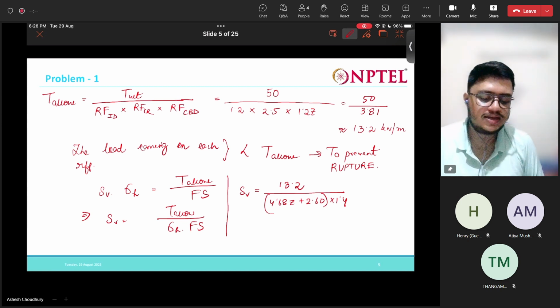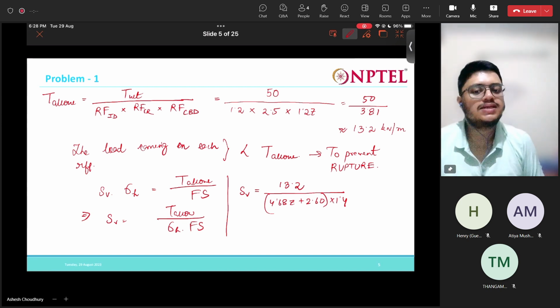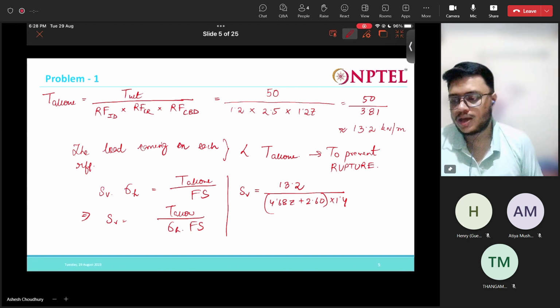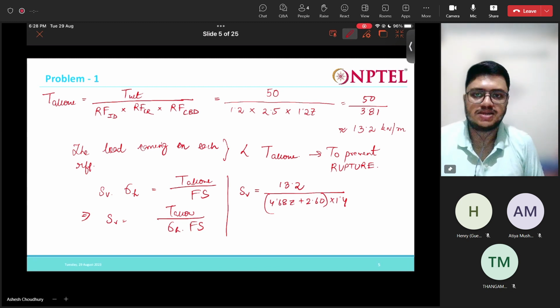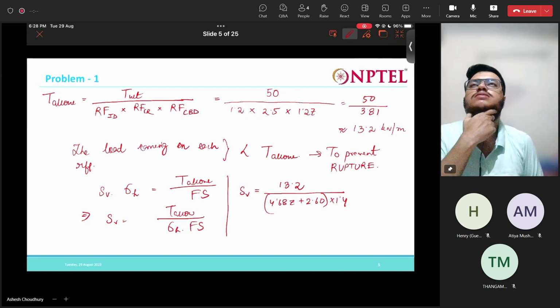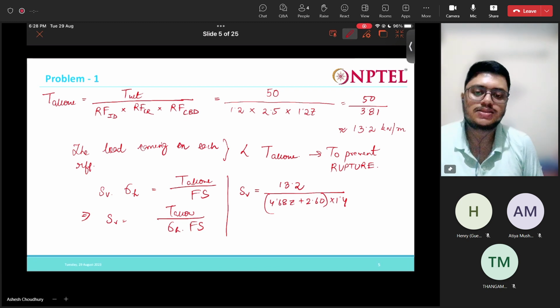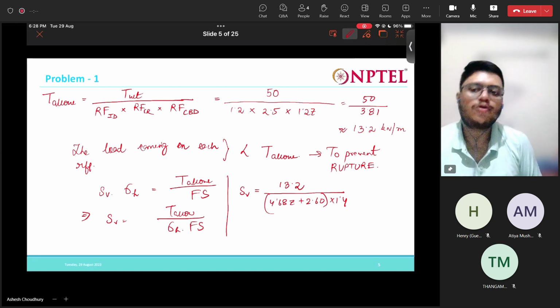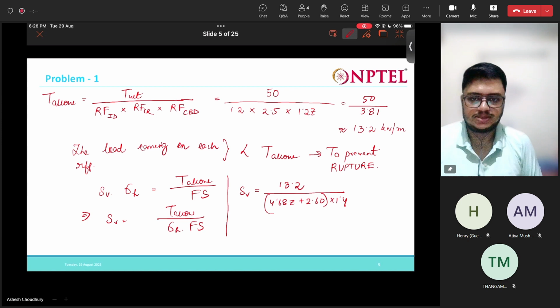You can see, if z increases, this spacing is going to reduce. Now what is the height of the wall? 6 meter. We are to construct a wall of 6 meter height. So the maximum depth is 6 meters. Now let us find the spacing for 6 meter depth.